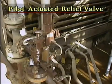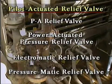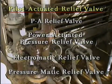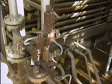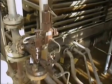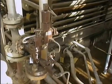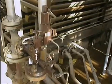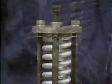This is a pilot-actuated relief valve. It may also be referred to by any of these other names. Pilot-actuated relief valves operate much like safety valves. That is, they pop open rather than open gradually, and they have a predetermined amount of blowdown to prevent chattering.